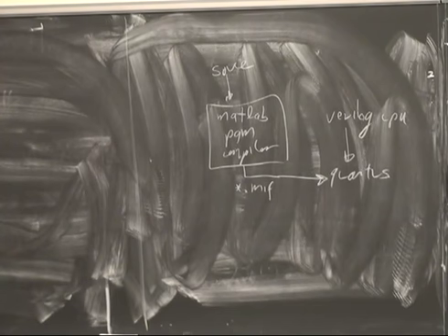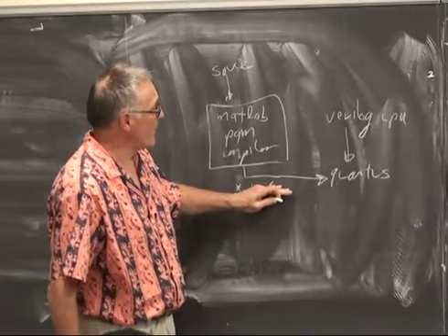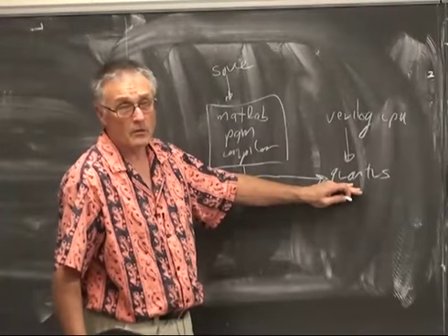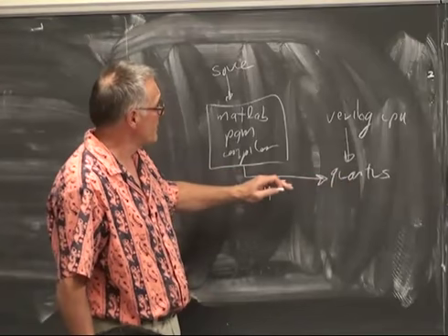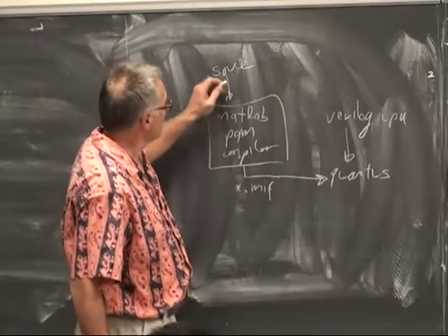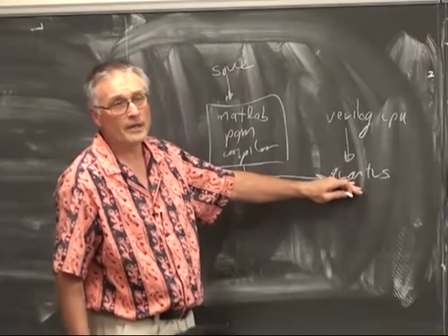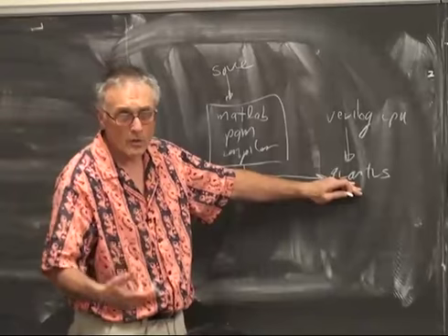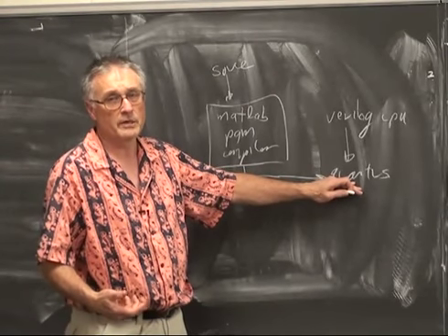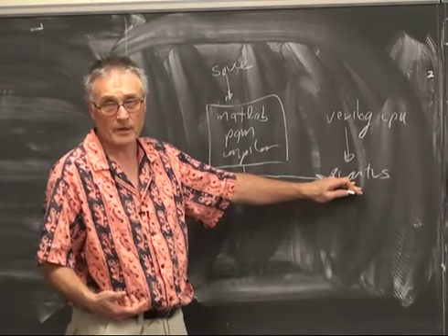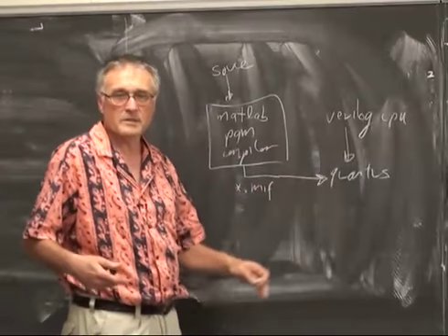Once you have identified the MIF file to Quartus once, then you can do this compile, generate MIF, modify in Quartus without going through the whole system generation, but rather bypassing the system generation and just updating the memory image file. So it's a fairly fast compile, run, test sequence.